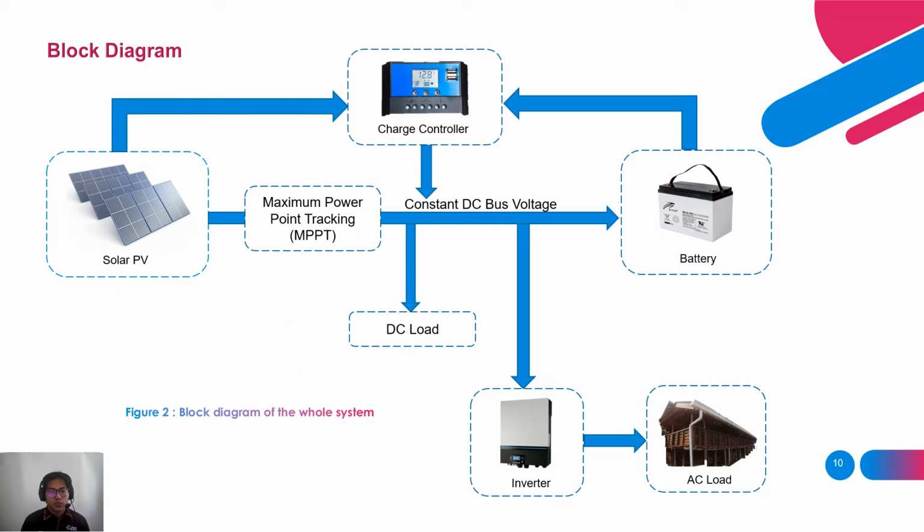This system consists of solar PV with MPPT, battery storage, DC load and AC load with inverter. PV panel will act as generation after receiving the solar irradiance from sunlight, supplied to the battery and load. The maximum power point tracking block designed in the system is to detect the power condition of the photovoltaic panel to be supplied to the battery system. An MPPT controller will convert the input voltage to the correct voltage for charging the battery. Inverter is a converter that converts DC energy such as from the battery to be used by AC loads. Meanwhile, the controller tries to maintain the constant DC bus voltage in a varying load and solar generation scenario.